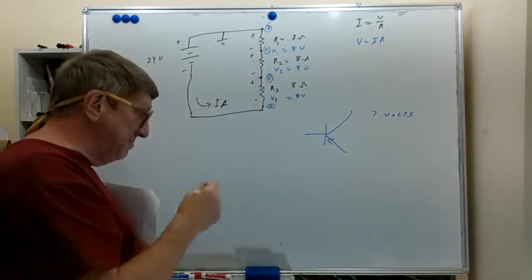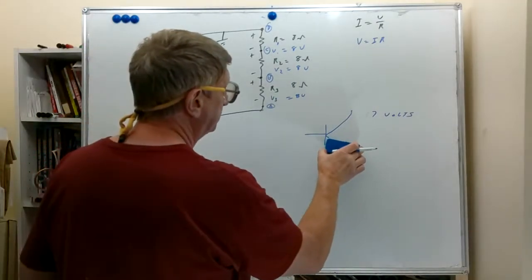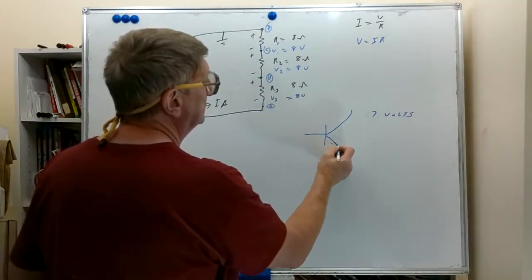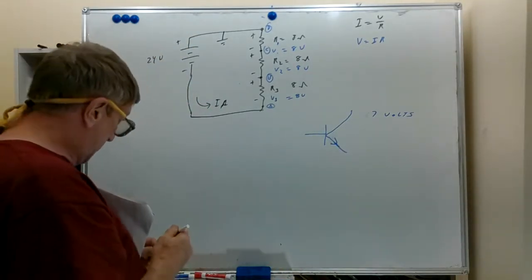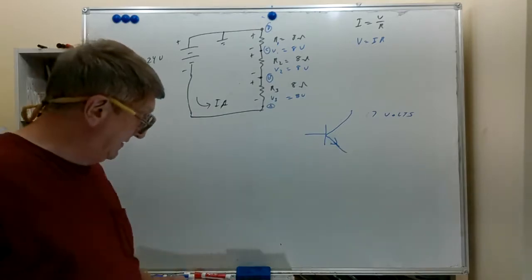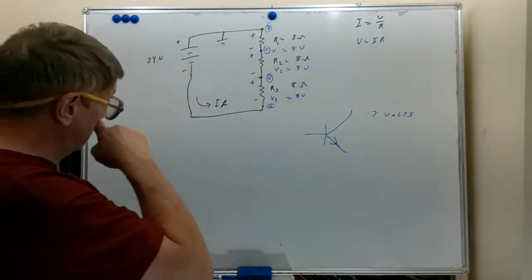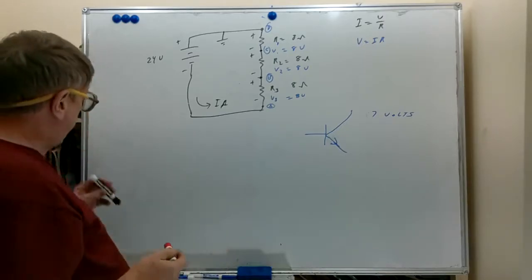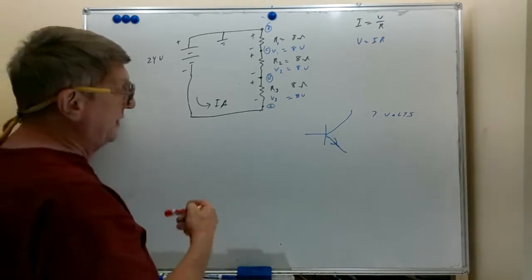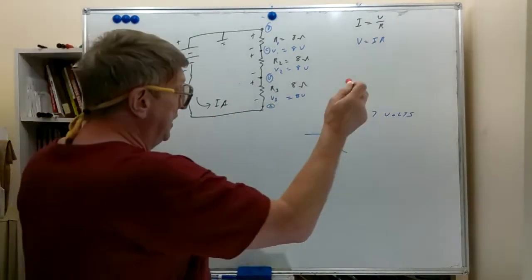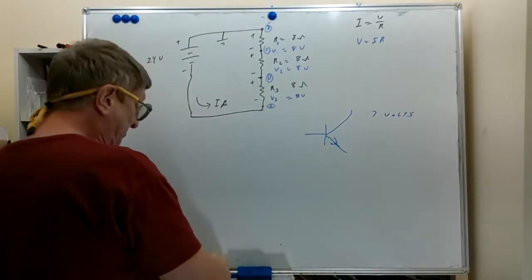What that usually means is that it is the voltage relative to ground, referenced to ground. If you just see a single number on the schematic, that pretty much means if you touch your meter to the case of the radio or whatever device you're working on, and things are working right, you should see 7 volts.